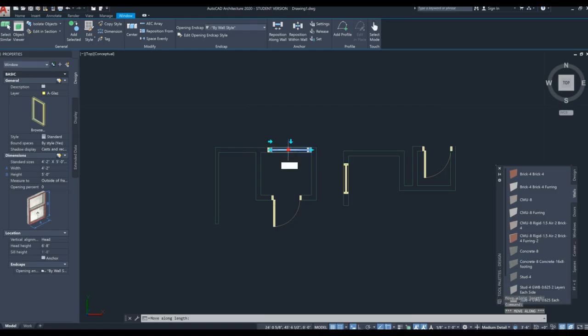Now this won't move. Okay, so you see how I can't move this to the exact correct position? If your mouse is not doing a good enough job, you can use the nudge tool. So I hold Control on my keyboard, and I want to nudge it to the right, or to the east. So I hit the right arrow while holding Control, and I click the right arrow multiple times, or I hold down, and it's slowly nudging over to the side. This is better for fine tuning. It's not great if you have large distances to move.